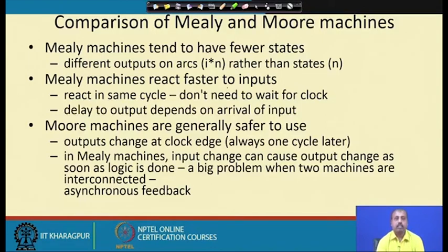As a result, many Moore machine states can be combined in a Mealy machine state, because for a Moore machine, two states that are otherwise the same, with only the output being different, constitute two different states, whereas for a Mealy machine they can be clubbed into one state and we can represent the transitions by means of the inputs also.